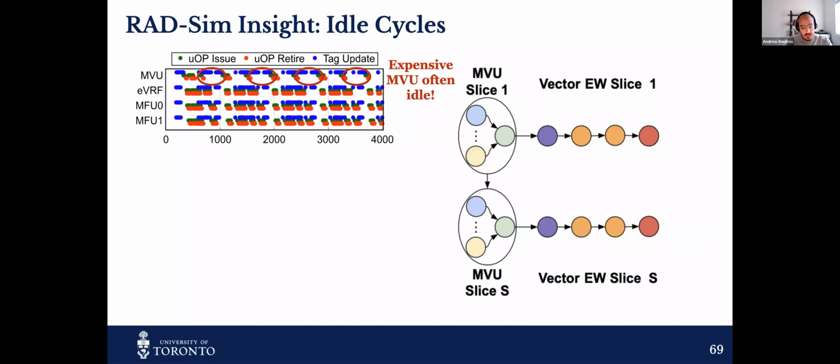And this is an artifact because the NPU runs AI models that have dependencies across time steps, for example. So the NPU would remain idle until the output of the first time step goes back to the NPU, and then you can compute the next time step, which causes these idle gaps in the NPU execution. And once you introduce a realistic NoC with congestion in it, this latency becomes longer and causes degraded performance because of these idle gaps.